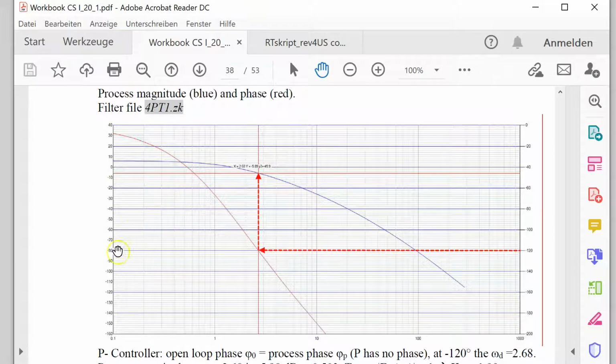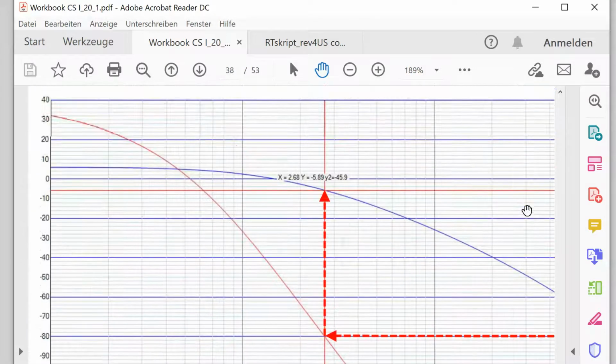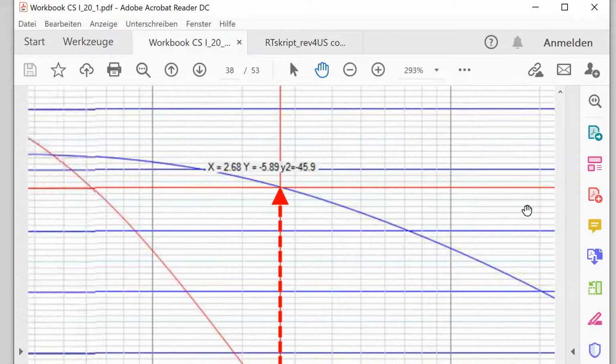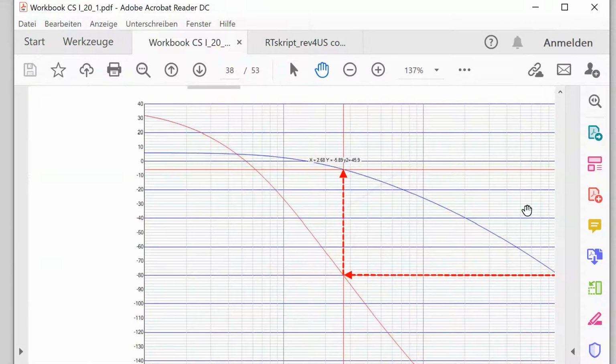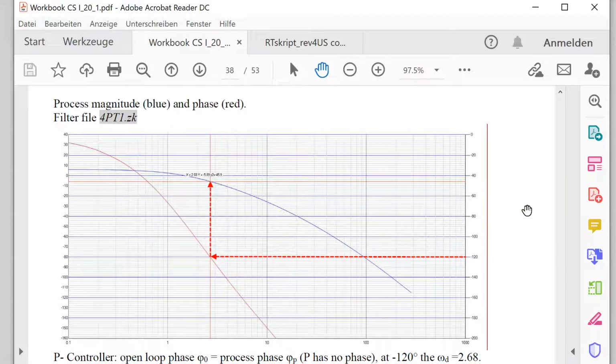Here we have big lines between 20 dB. Here big lines also define 40 degree phase value. I can make this curve larger with my fingers. I have a touch screen, so I can show you some more details. You see there are some lines here. These lines will be explained now in the next step.